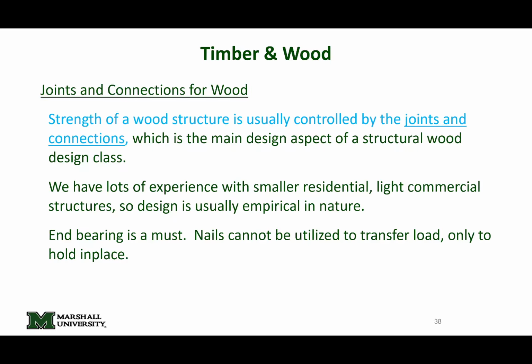I have this statement here in the slides that the strength of a wood structure is governed by the strength of its connections, and that's true. We're going to spend a good bit of time in timber design looking at connections, but this is also true of any structural system. If a member fails, the member fails. But if a connection fails, multiple members fail, because multiple members connect at a connection. That's what a connection is. So connections are treated with higher factors of safety. Your resistance factors are a little more stringent in connection design than they are in member design.